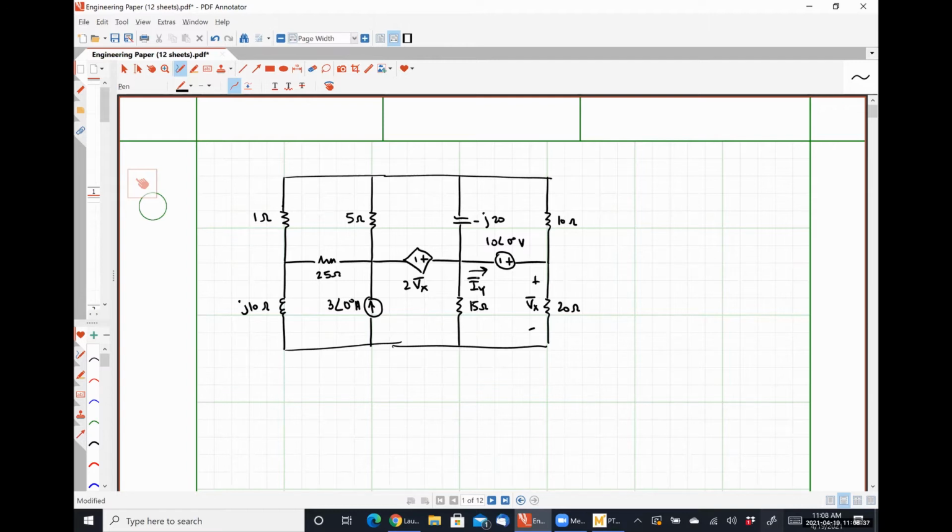So this particular question looks mean regardless of whether we do nodal analysis or mesh analysis. So which one would you prefer? Mesh, okay. So if we do mesh analysis, perfectly fine. We're going to have 6 equations and 6 unknowns. Well, actually 6 equations, 1 for each mesh. And then we're also going to have to find an equation for Vx in terms of mesh currents and all that kind of stuff. So it's going to be 7 equations, 7 unknowns.